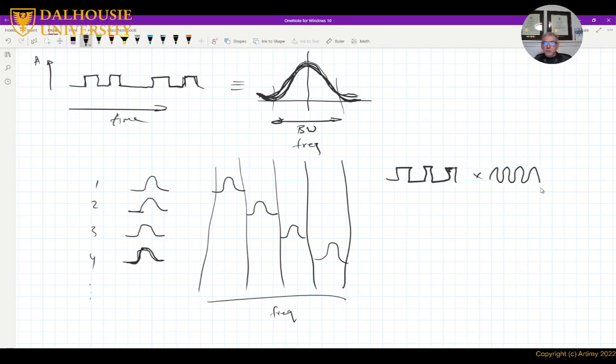So in amplitude shift keying, we can take the signal, multiply it with a sinusoid wave with a certain frequency, I call it carrier frequency. What we end up with is a signal where there is 1 and no signal when there is 0, right? So that effectively shifts the spectrum from around 0 here to around FC1.